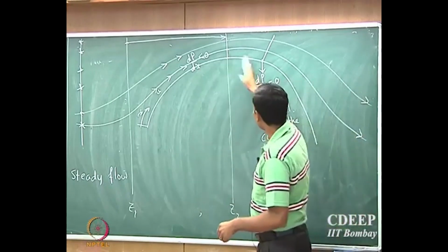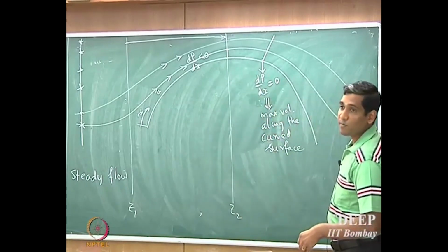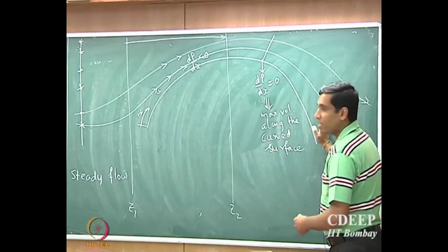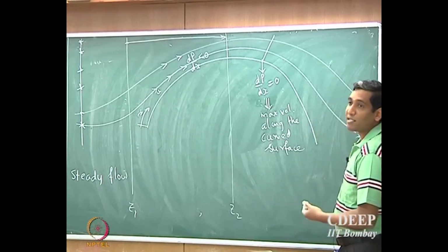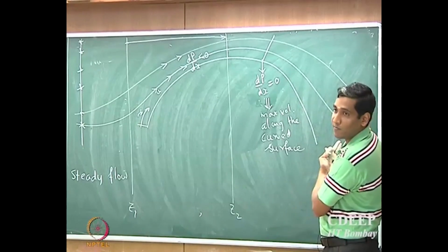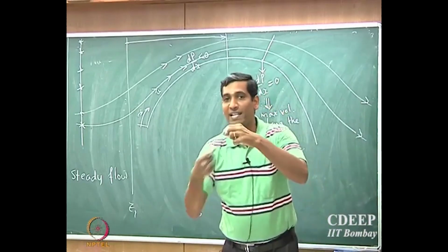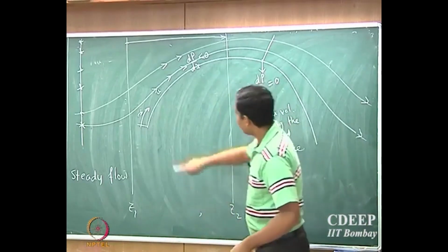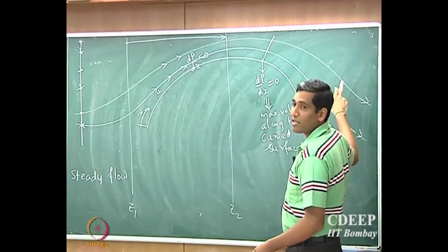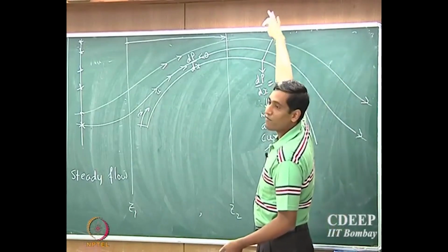But when the fluid particle leaves the cylinder, it cannot have any acceleration, because it's now traveling the same distance as the other fluid stream after the fluid has left the cylinder. So therefore there has to be a location where the fluid particles are decelerated, so that the increase in velocity needed to catch up is decelerated until it reaches the same velocity as that of the free stream fluid.